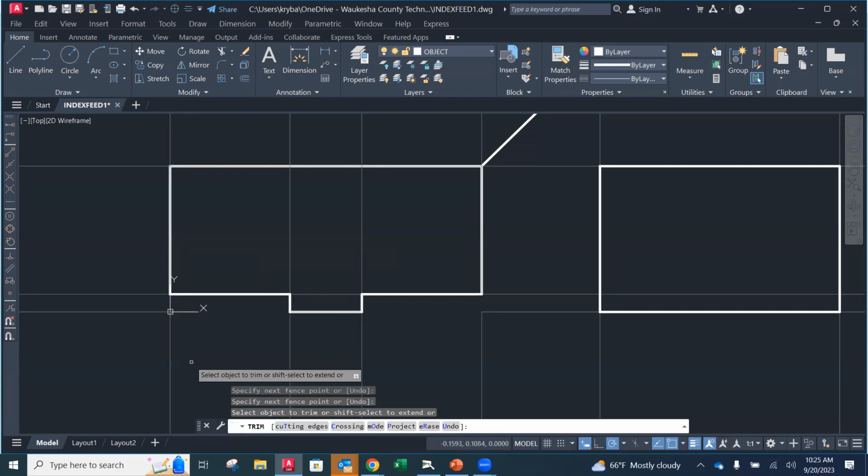It's because I think the construction line is in the background. It doesn't know which one to pick. I think it's kind of obvious in AutoCAD, but whatever, it's fine. It doesn't recognize it as a construction line step. Well, I did do it as X, the construction line first, because it was the first one that we created. Anyway, you've got to do that for those trims when you're doing it over the top of a construction line, I noticed.